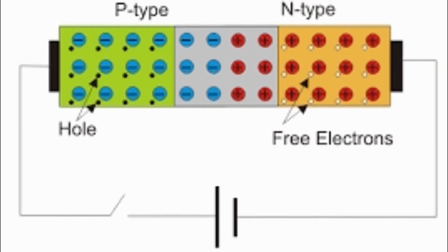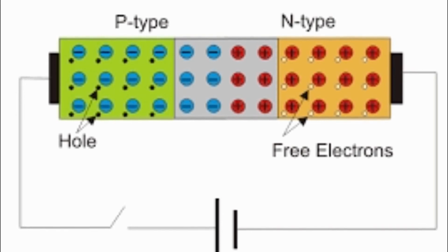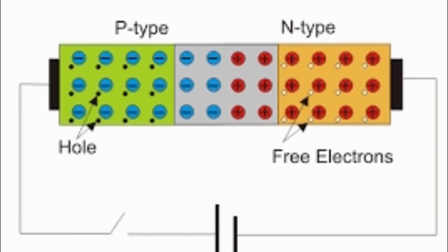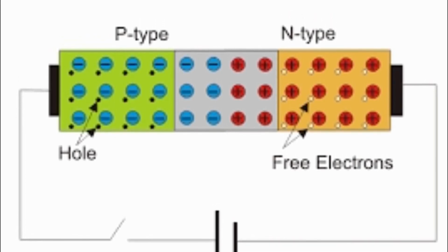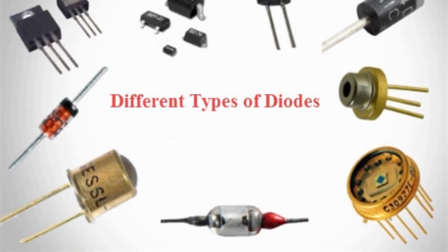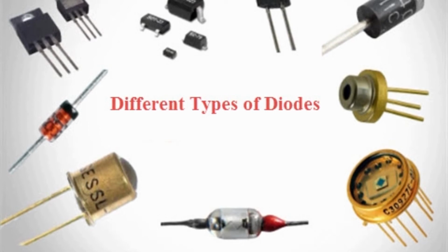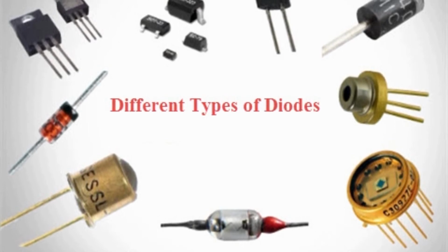Avalanche diode: This diode conducts in reverse bias condition, where the reverse bias voltage applied across the PN junction creates a wave of ionization leading to the flow of large current. These diodes are designed to break down at a specific reverse voltage in order to avoid any damage.